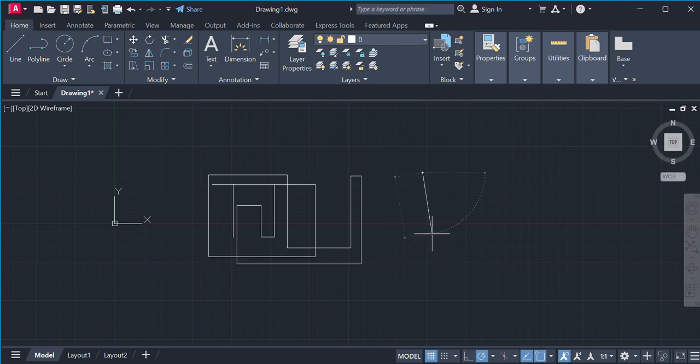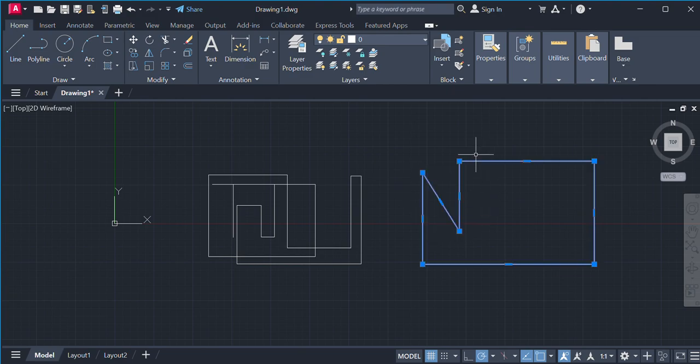Then we're gonna use the Polyline command. The Polyline command acts almost identically to how your line command would behave. The only difference is that with a Polyline command, once you exit the command, everything you've drawn is essentially one big object. Everything becomes a family, as opposed to your line command, where it's every man for himself. Every line acts individually. If you want to delete a single line, you can. If you want to delete everything at once, you would have to select everything using a range of selection methods.